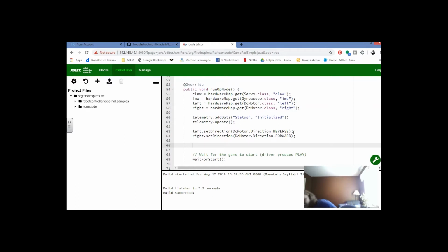Now, I'm going to hold up my servo motor so you can kind of see. The servo motors, they're not super powerful. They don't have a ton of torque unless you get special high torque servos. So just count on them to do small things like operate a claw or a sweeper arm or something like that. This claw in this example, I want it to start in the up position and then move down to about 90 degrees when I push the trigger.